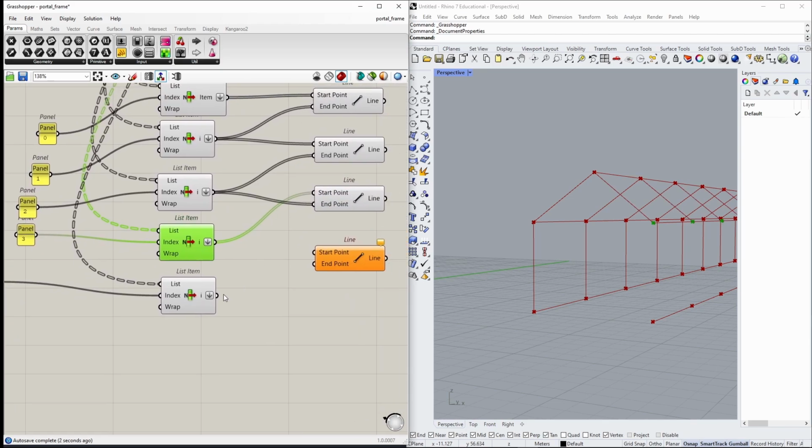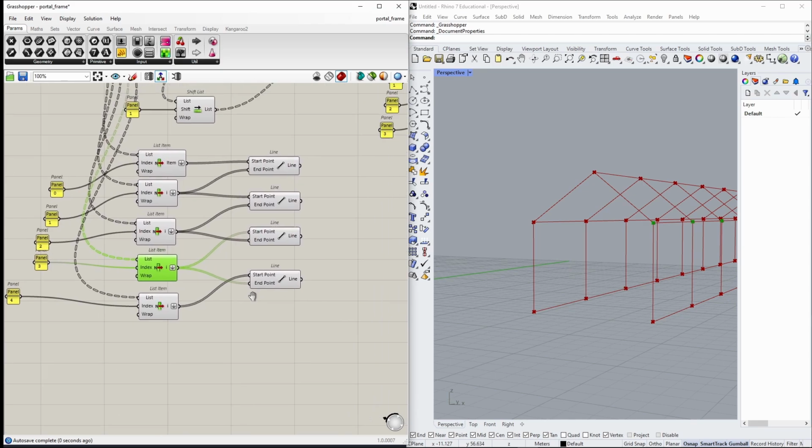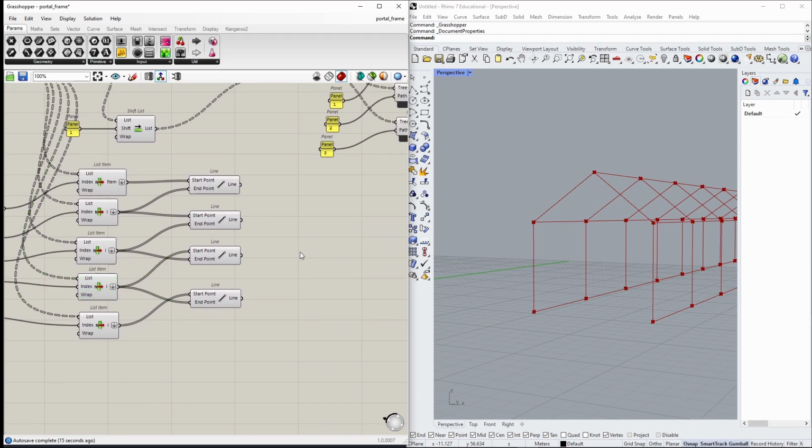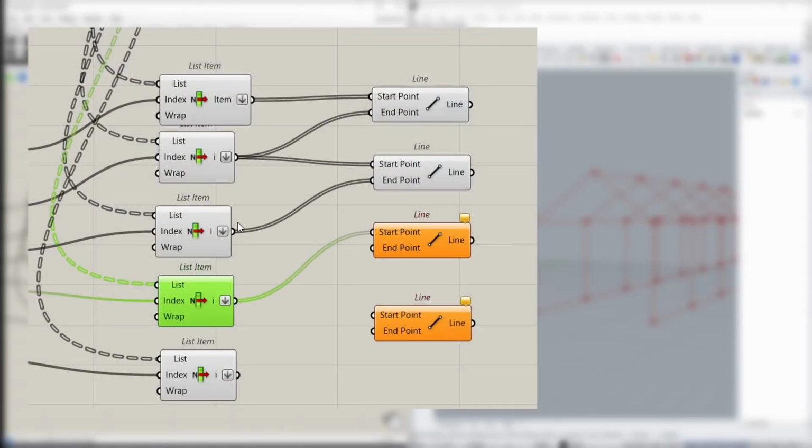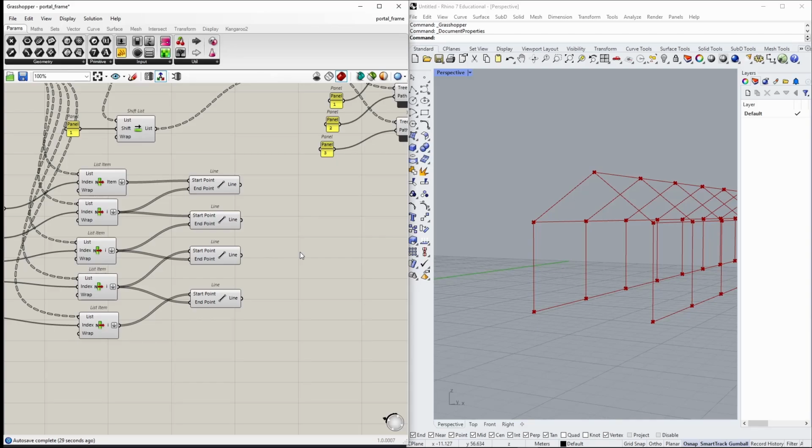For the last line, the last list item is the start, and the second to last is the end. On the rafters, we usually see the purlins, which we can create in the following way. Thanks to the last step, because in that we created the rafters in a way that every one's endpoint is the apex, meaning the line's directionality is towards the highest point. This comes in handy in the distribution of the purlins.